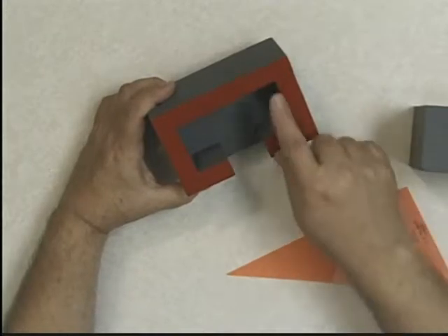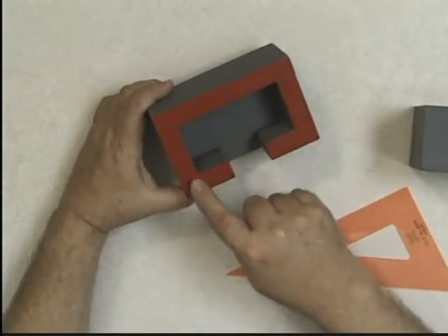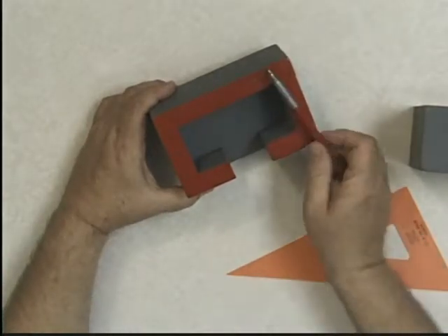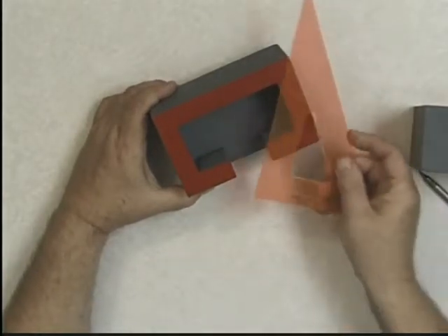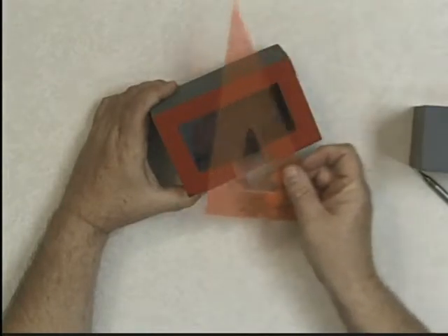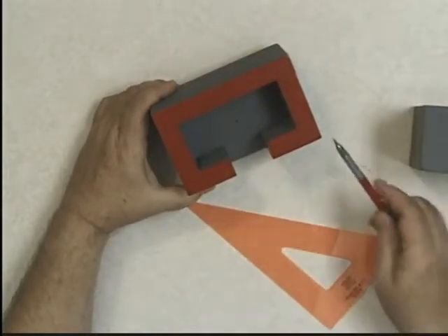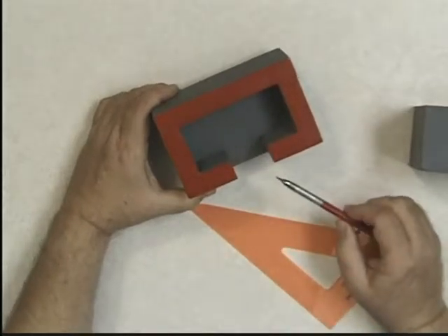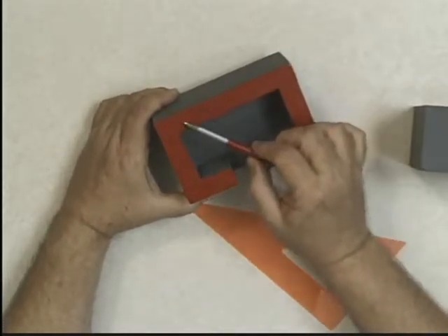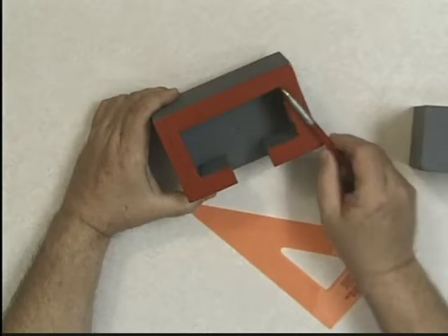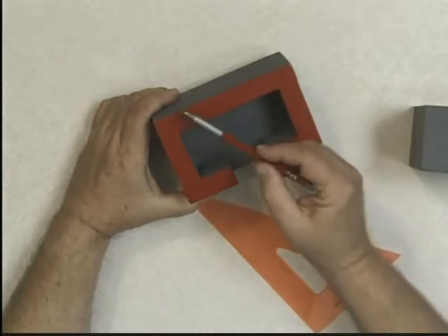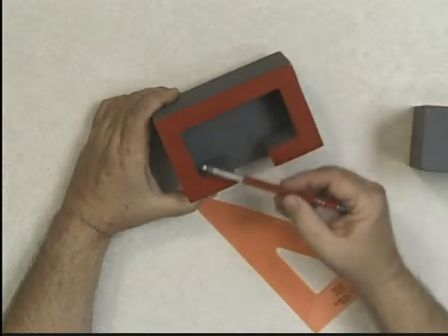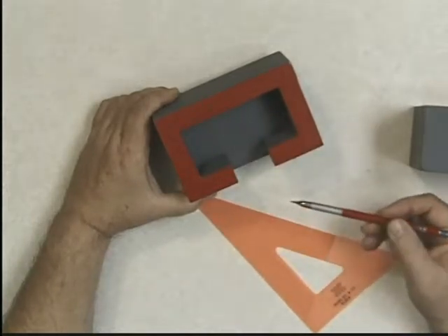Now, I've taken this object and I've painted part of it red. The part that I've painted red is the part that was actually contacted by the cutting plane itself. Actually, I won't paint them red in an engineering drawing. In an engineering drawing, all this part that's contacted by the cutting plane will be shown by constructing something called cross-hatching lines, very evenly spaced thin lines. You'll see more of those before we're done.